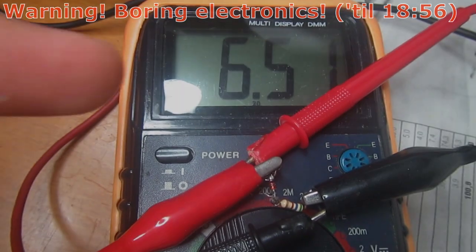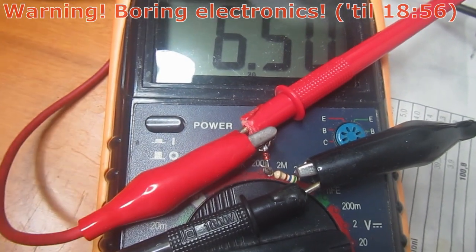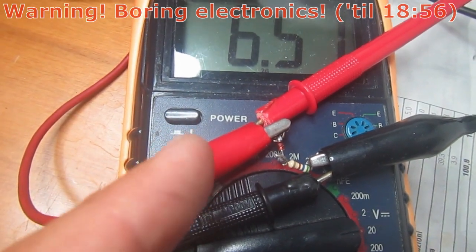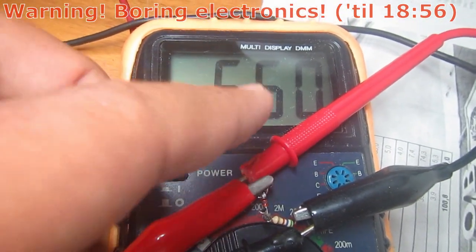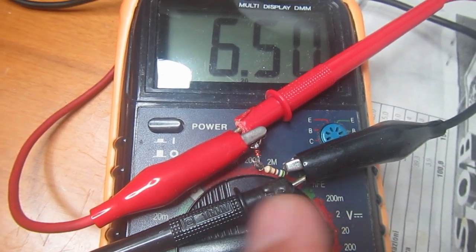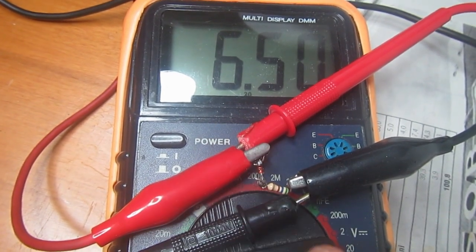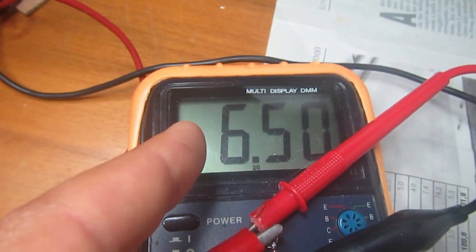Now before changing the actual zener diode voltage, let's understand if maybe this zener diode has a little current leakage at, for example, 6.5 volts. So I'm using a variable voltage supply, which is hooked to the zener and resistor combination, just measuring the power supply voltage that I set at 6.5 volts.